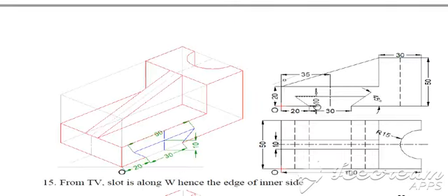So now we find that this distance is 30 mm and this top distance is 50 mm, and the distance between these two lines is 10 mm. By using that, first from this origin point this distance is 20 mm, so mark the distance of 20 mm, and further then it is 30 mm, so mark the distance of 30 mm. From this 30 mm point, basically you are supposed to draw a 45 degree line, but as I have just explained, you can't mark the angle.